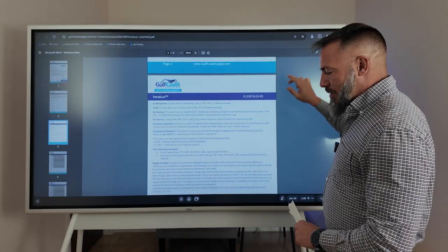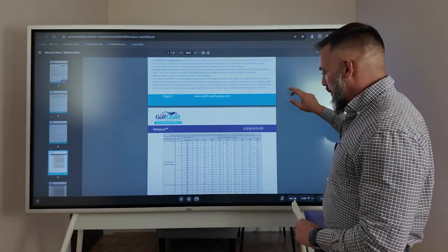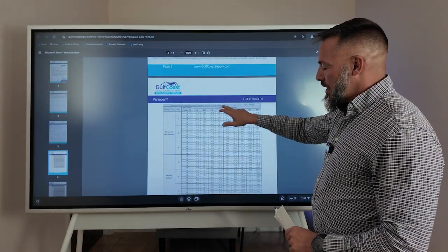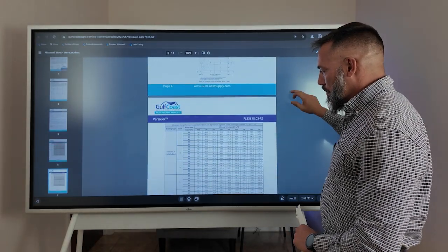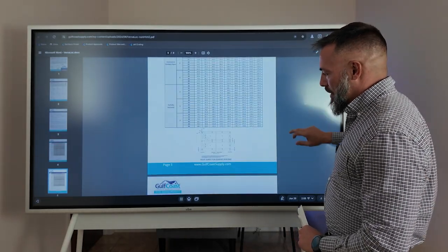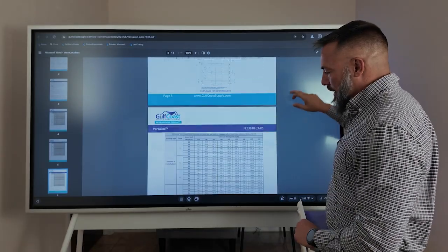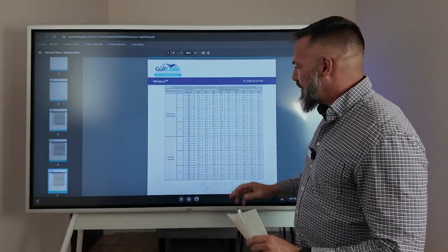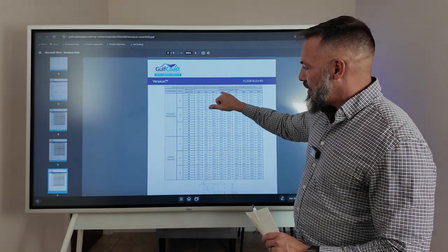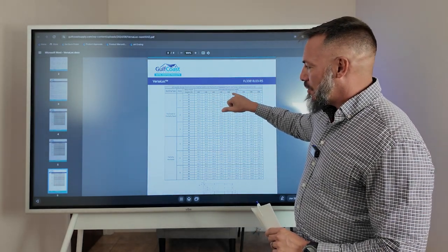There will be conversion charts on the bottom. Here you can see exposure B. We said we have an exposure D structure because we're right on the beach. The next one is exposure C, and the next one is exposure D. So we had 154 mile an hour winds. I don't have anything in between, so I have to bump that up to 160.